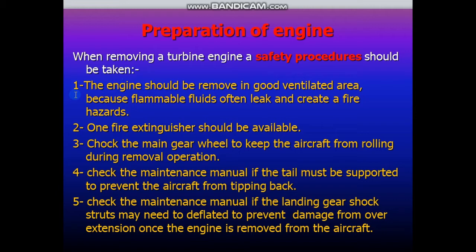The fourth procedure: check the maintenance manual to see if the tail must be supported to prevent the aircraft from tipping back. Number 5, check the maintenance manual to see if the landing gear shock struts need to be deflated to prevent damage from overextension once the engine is removed from the aircraft.